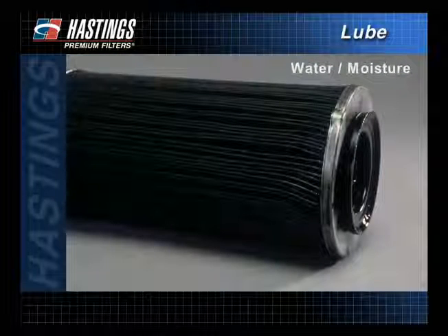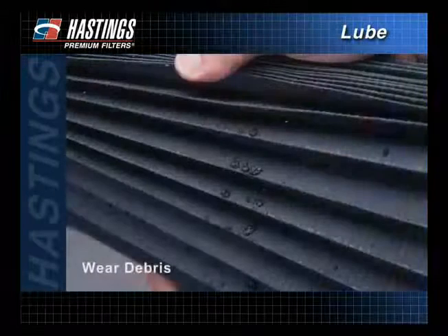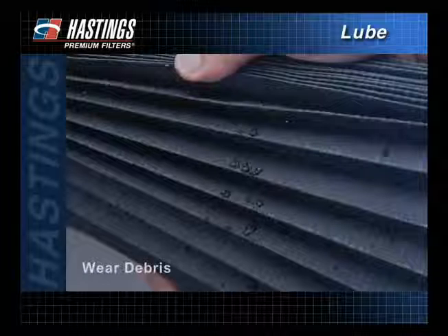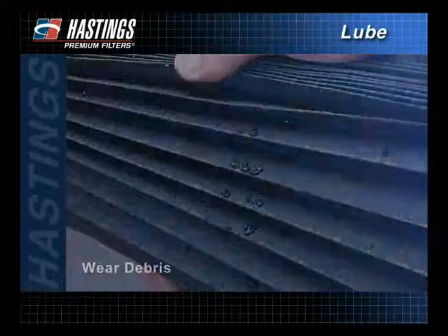A deteriorated outer wrap is another sign of moisture. Certain oil additives will trap water and cause a gel-like coating on the filter media. It may appear clean, but when tested, will show a restriction if moisture is still present. Any wear debris on the media is a sign of trouble.